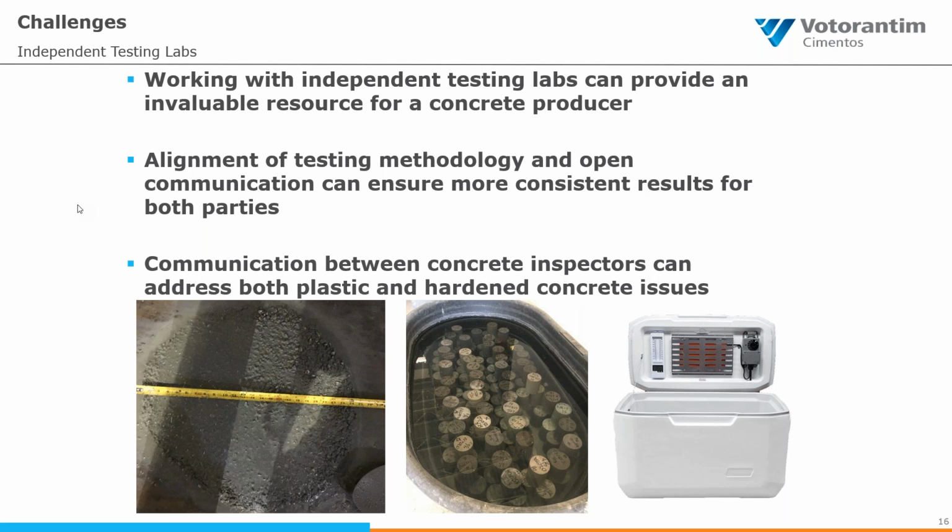So aligning your test methodology and the lab of record's test methodology is a huge benefit because you at least know you're on the same page and you're doing things the same way. So it's much easier. I strongly recommend, should you try to partake in any of this, you make sure you have proper conditioning for cylinders, proper storage, whether it's the expensive cooling boxes, whether it's just tanks of water, because